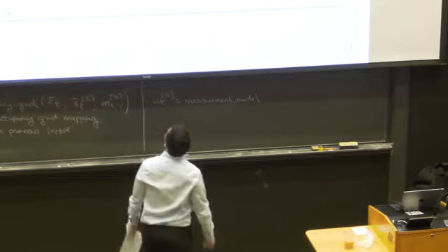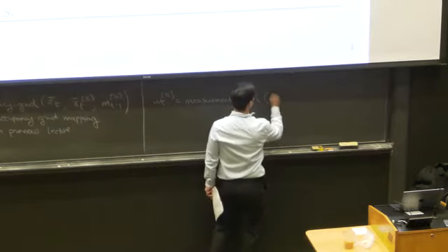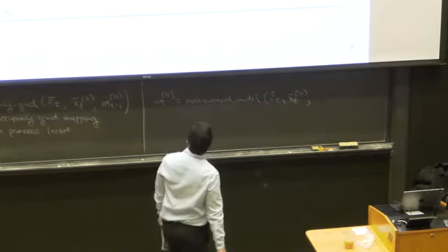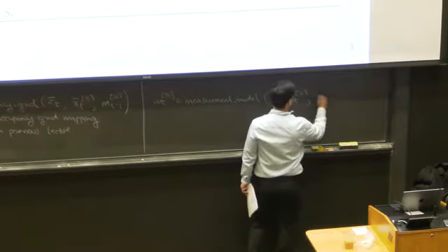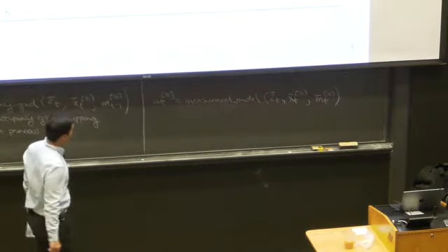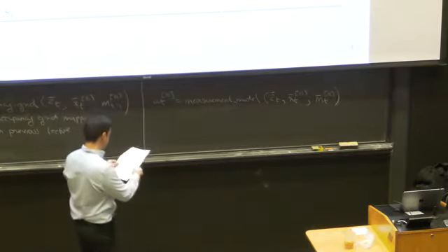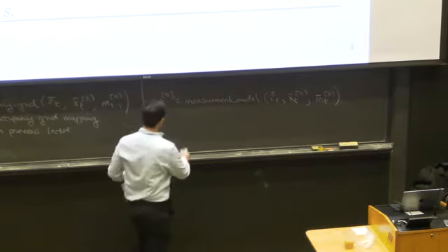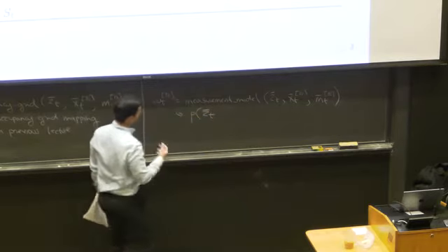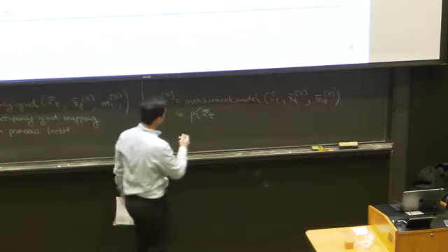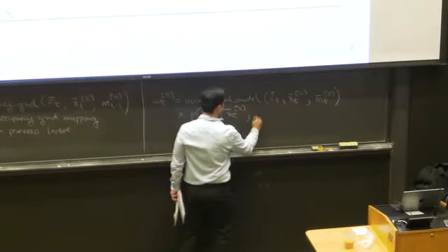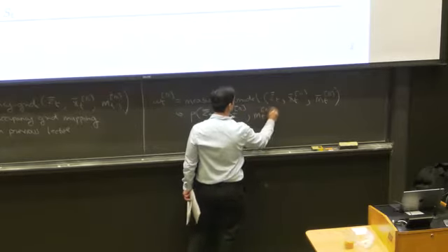This is taking in 3 arguments again: z_t, the current sensor measurement, x_t^k, our best estimate right now of the location, and m_t^k, our best estimate right now of the map. And what this step is doing is computing the likelihood, P of z_t, the likelihood of receiving the sensor measurement that the robot received right now, given the location and the map.